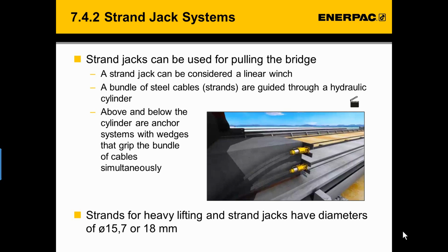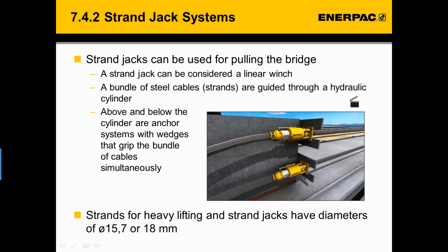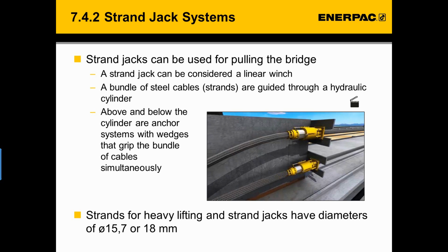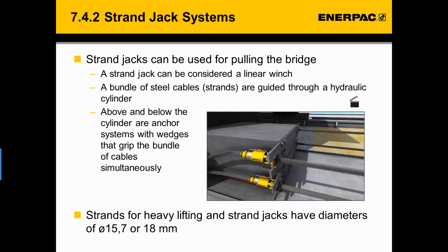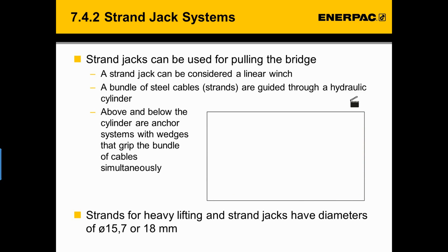Let us see the application of strand jacks when moving a bridge construction element. The strands used in the heavy lifting strand jack applications have standardized diameters of 15.7 or 18 millimeters.